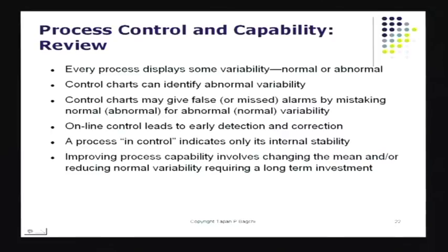If the process is being influenced by a lot of these abnormal causes or assignable causes, spend some time to try to remove them. Once you've removed them, what is left is just the chance causes. These are the random factors that will be there no matter what, unless you improve the technology of the process. If you improve the technology, you can of course tighten up the process. That's one great way to try to improve a process. So control charts would be a pretty decent place to begin your study, and take a look at just in case these charts show some sort of abnormal variability.